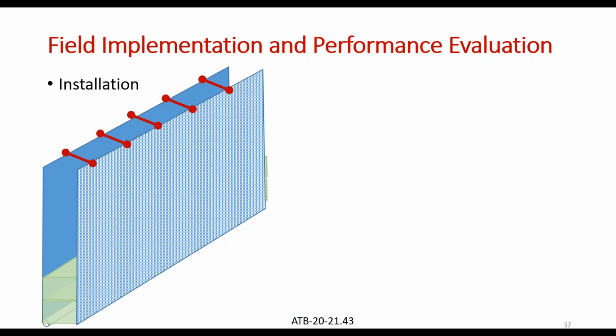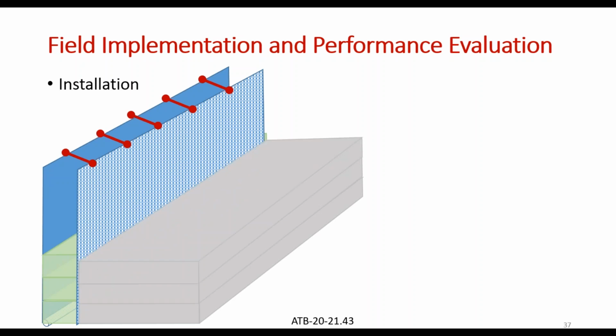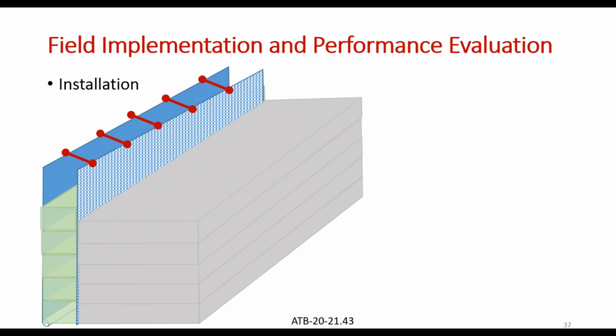In that case, you have a larger width, as well as the possibility that you can destroy or damage the fabric. So probably you need to stop there, place the backfill, compact it until you have better support from the other side. You can place more porous backfill, and then you can complete it.